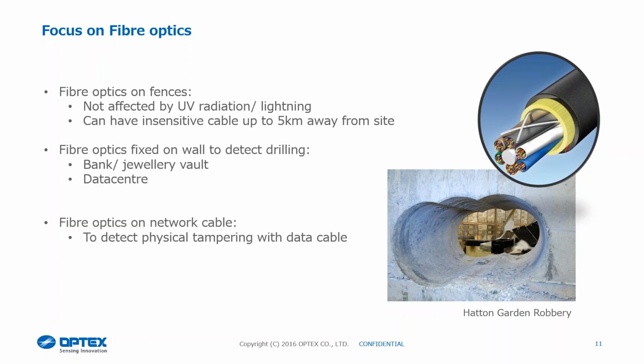With that last part, anybody trying to go below a fence line, you need to have in consideration what the ground type is like. There's no way you're going to get an activation if you've just got loose soil below there. Somebody can potentially just dig that out. So if you are looking for a detection if somebody's going under the fence line, you need to make sure that's dropped into a concrete plinth.